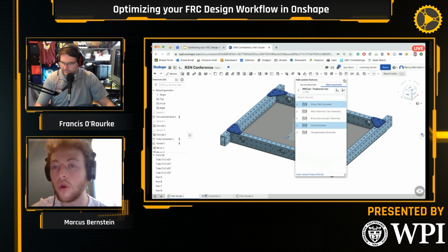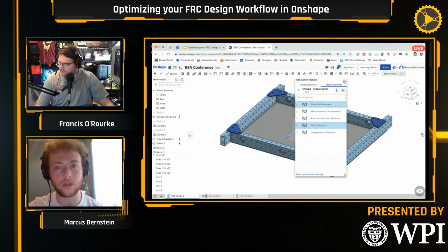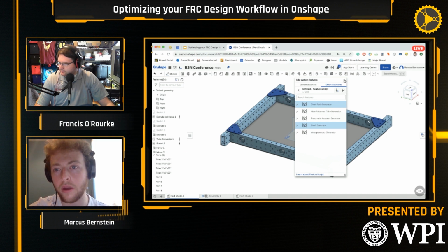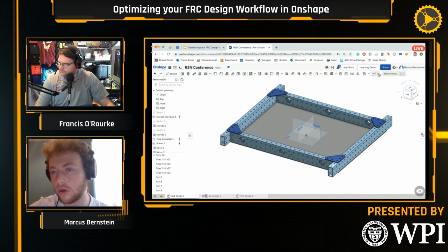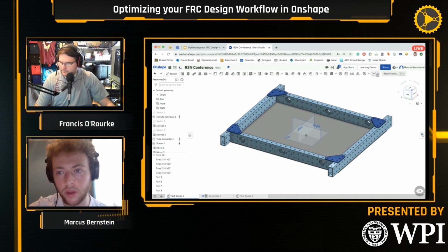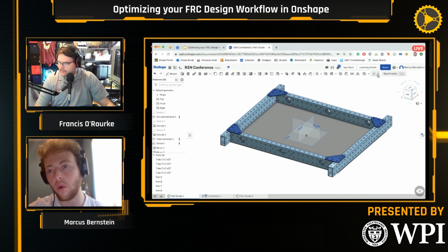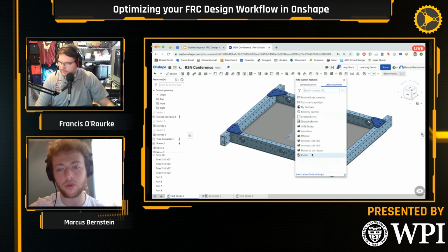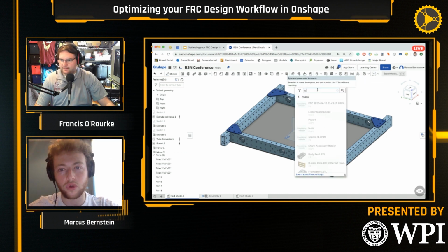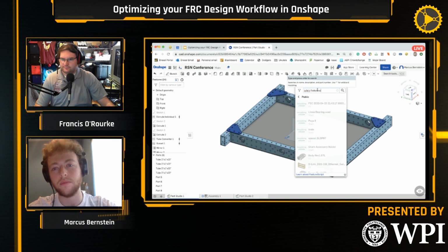The other ones that I showed today are created by Julia Schatz, and we're debating putting those into MKCAD or not. That's a conversation that's actively being had now. But I'll do another quick demo of how you would pull those in if you really wanted to. If you go to the plus right here, or in the dropdown, add custom features, public, you just search Julia's feature scripts.